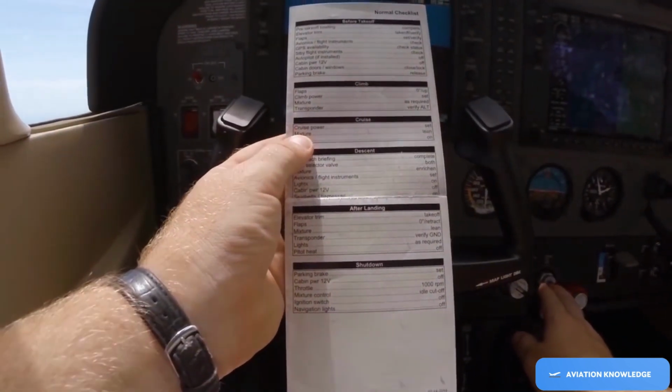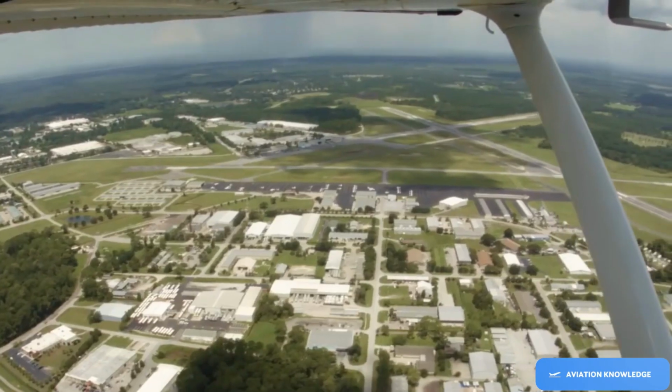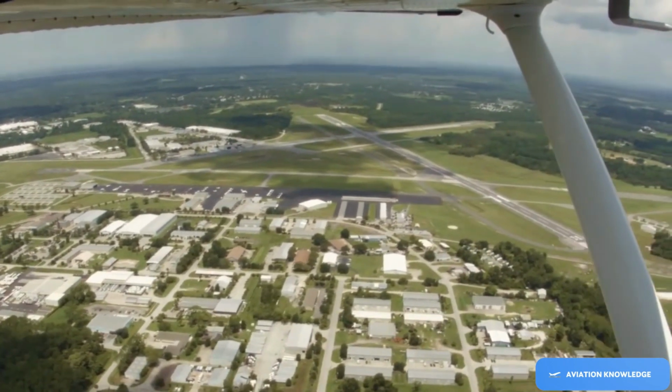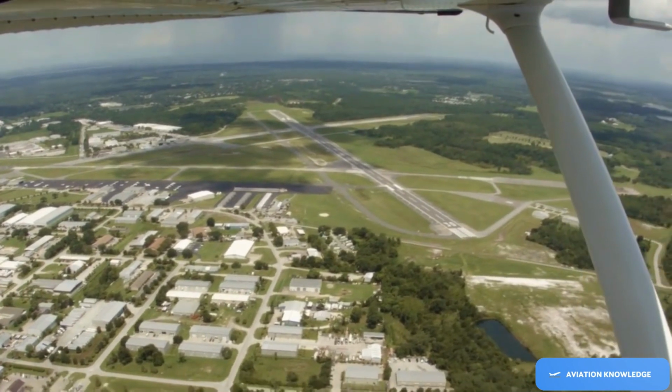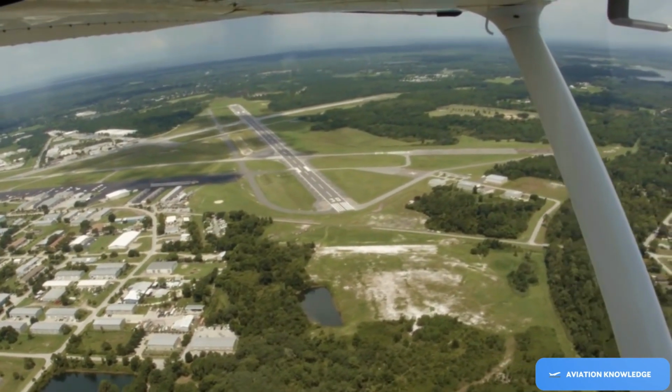That will keep you from any extra distractions during your final approach. As you approach the airport, use either the traffic pattern procedure outlined earlier or the instructions given to you by ATC to position the airplane on downwind and select the point on the runway where you intend to land.